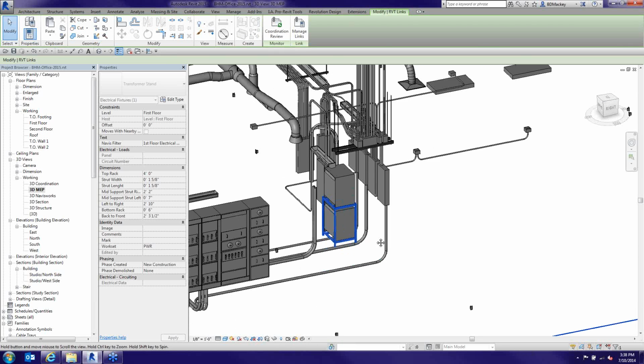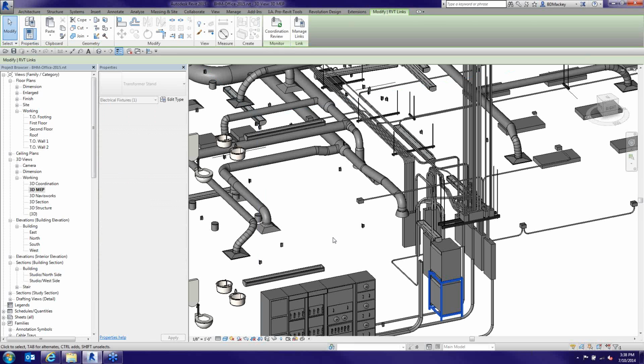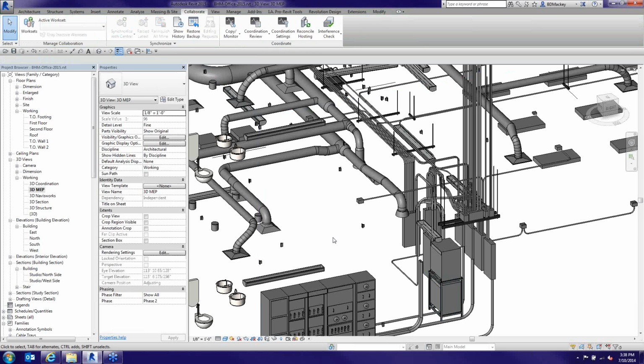They're also getting into like VAV boxes or anything that's in the ceiling that comes down and projects down, hey, I need this clearance for someone to be able to get into, on the floor, so you can't put furniture there. So as crazy as it sounds, sometimes I'll run duct accessories to furniture because I've got to have the clear floor space, or duct accessories to other things that we're not supposed to have inside of there. Actually, that's really a great tool.